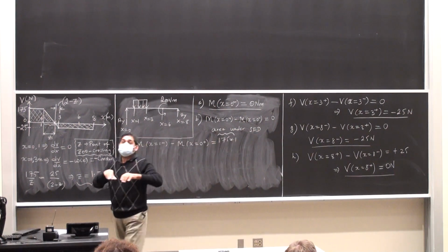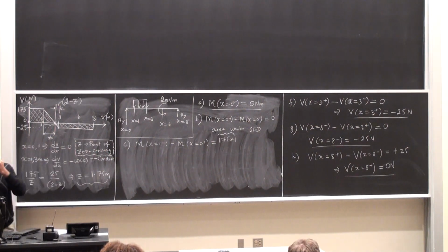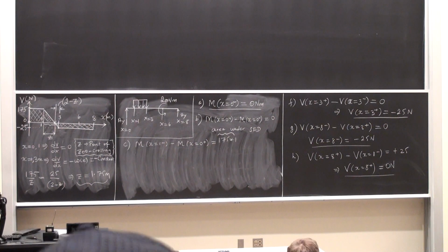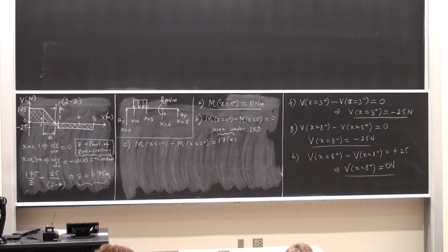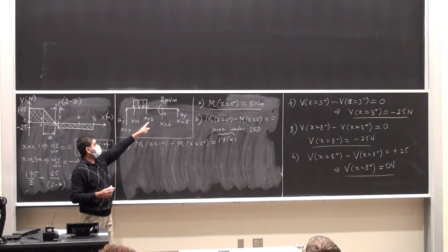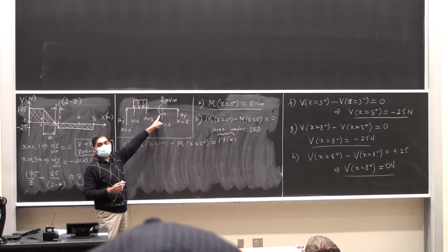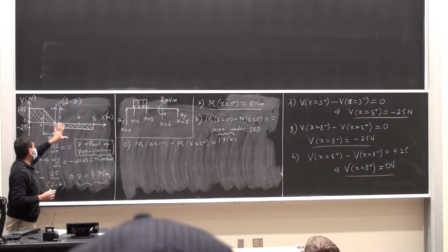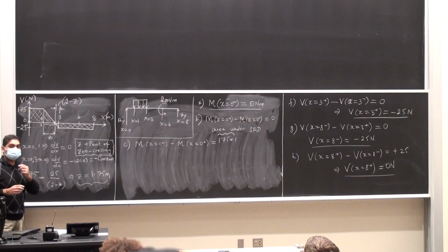Now you see why we need to have the shear force diagram to draw the bending moment diagram, right? Because everything is accompanied by the area. Yes, sir. So like in this case, you don't think about it creates a clockwise moment, the 175 force. You're only looking at the area under the curve. Absolutely. Okay. So the only reason why I have this is to deal with sticky customers like that. Otherwise, I am good to go with only the shear force diagram.